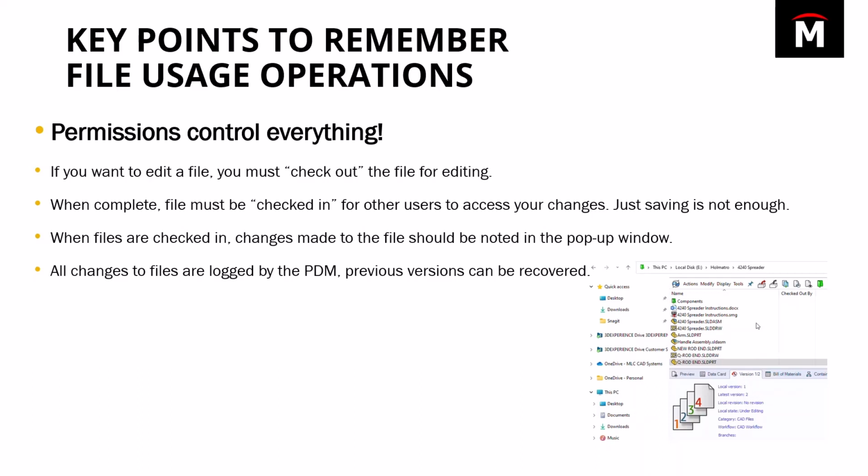During the check-in process, we actually advise that you add comments detailing the changes you've made so that other users can understand those changes. And just remember, everything's logged in PDM. The checkout, the check-in, the comments, all the versions of the files, old versions, they're all logged and retrievable from the PDM interface.